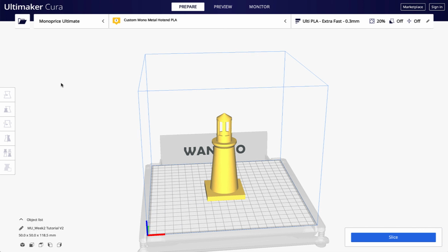Okay, here it is. So basically what I did is I clicked on here and then selected the STL file, and so it popped up like this here. Because we started designing it on the XY plane, it's already in the right location. If it isn't, you have these features here where you could actually rotate it and place it. But for us, this is good: in the middle of the printer bed, flat on it and upright. And so now we can just click on slice, right?